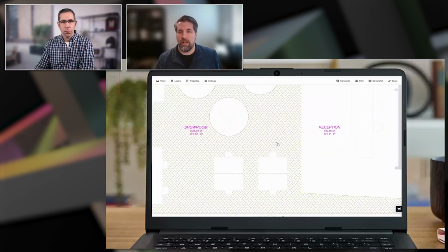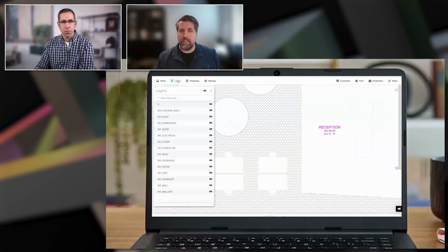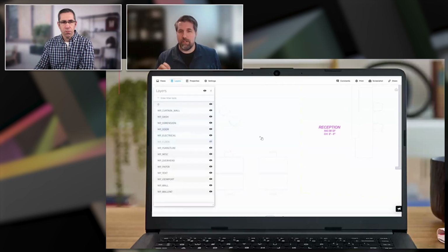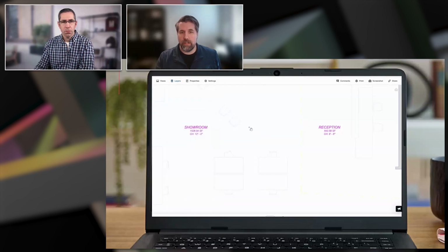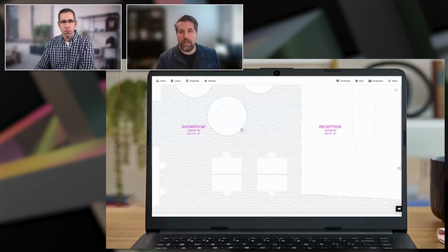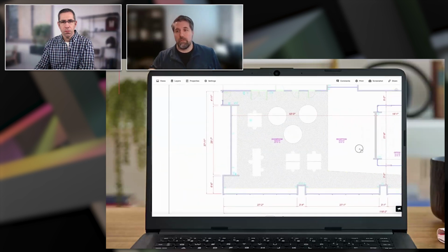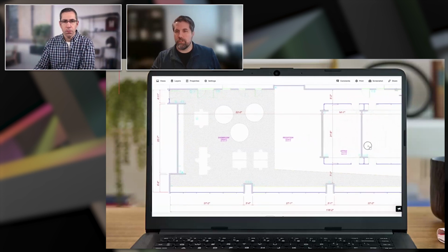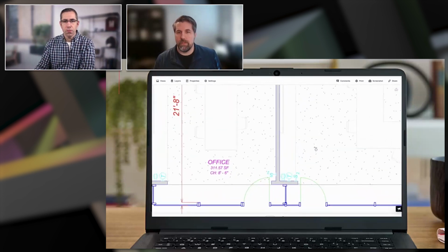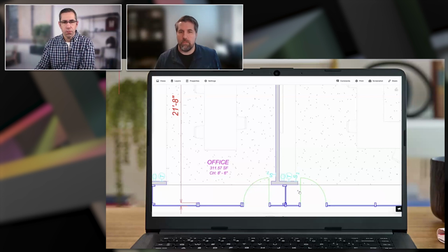Even in the different areas, we'll have the square footage labeled, so you can see that as well as ceiling height. And you can see when the ceiling height changes. So we're going to remove our floor layer here so we can clearly see these ceiling heights. If you zoom in, it's a little hard to see because it's yellow here, but we have a dotted annotation showing where that ceiling height changes. So you will still have information on ceiling height, even though it's a 2D drawing. We do include that and use those dotted lines to separate where the ceiling height changes. We'll also do that with sloped floors too. We'll indicate where the slope is and show how that changes. So you will have some annotation there for more than just the overhead view.